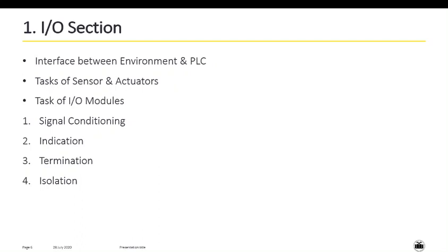At the second place, the input module is there. The input module converts an analog signal into a digital signal and amplifies it into the appropriate format by using an analog card, where the signal is amplified or attenuated to the required form. Okay, so the second block is your input module.